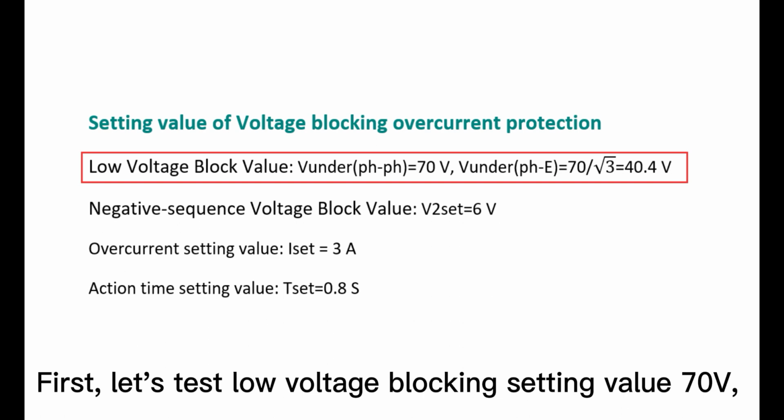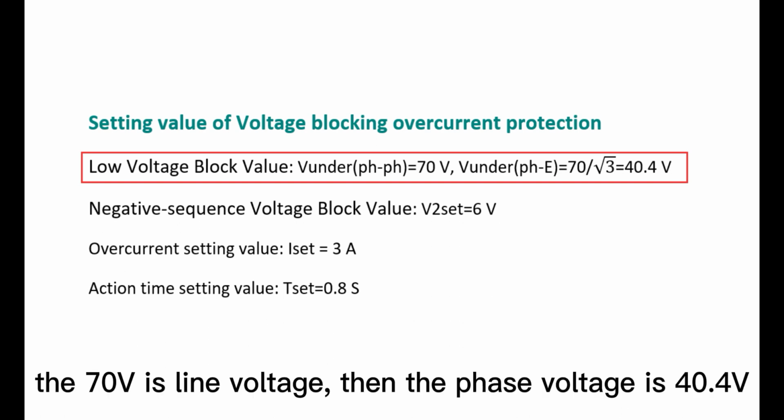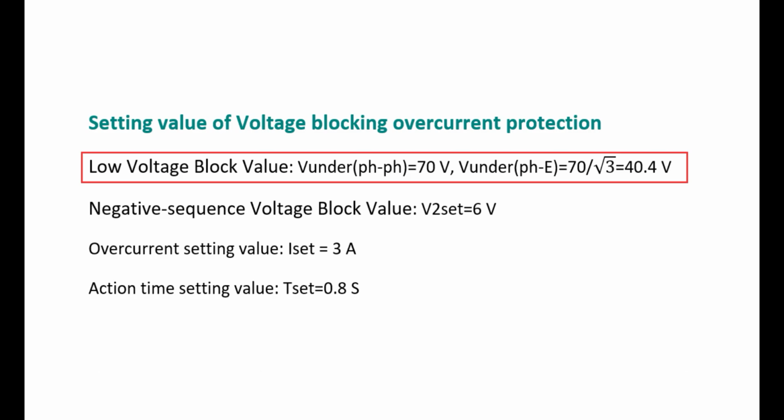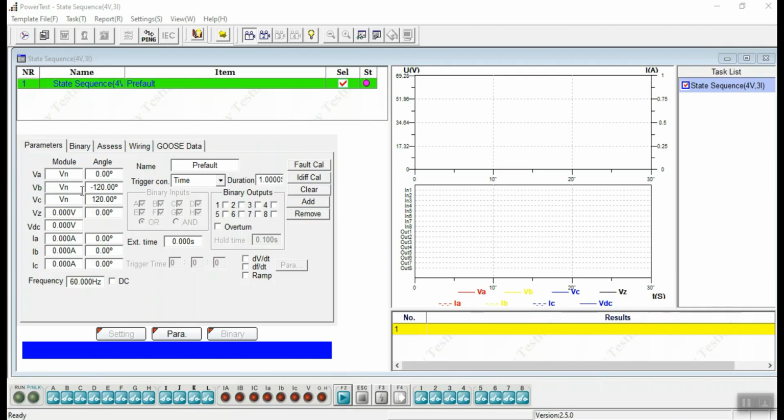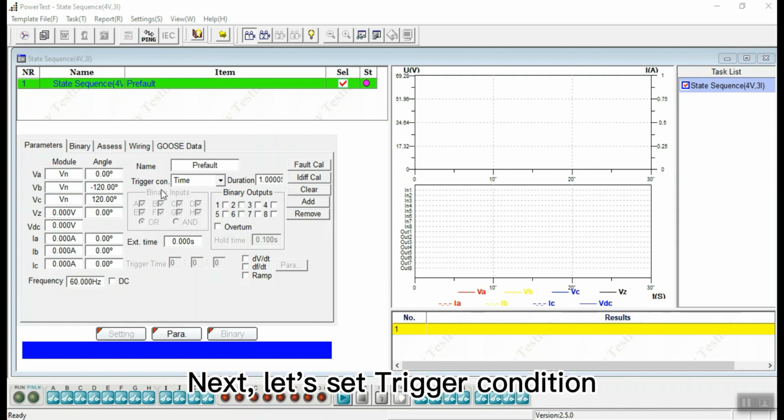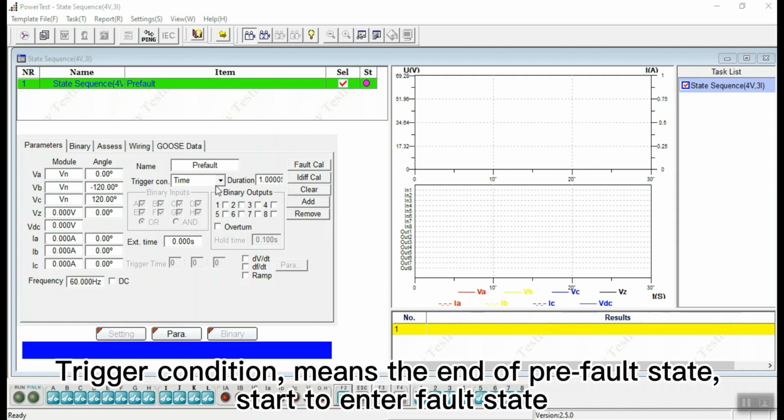First, let's test the low voltage blocking setting value, 70 volts. The 70 volts is line voltage, then the phase voltage is 40.4 volts. Pre-fault state is normal voltage. Next, let's set the trigger condition. Trigger condition means the end of the pre-fault state, and start to enter the fault state.